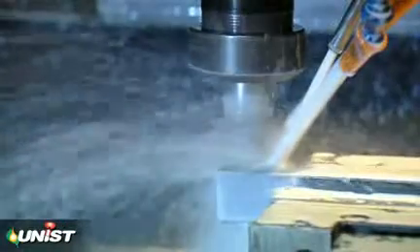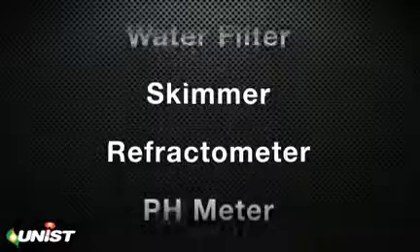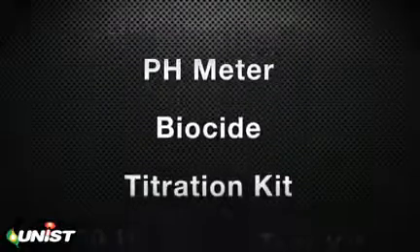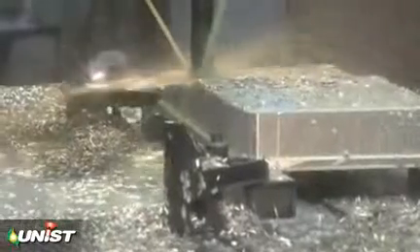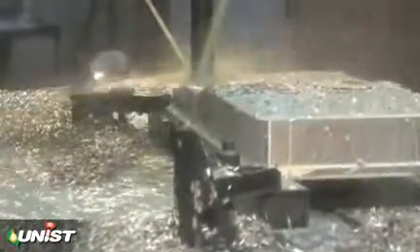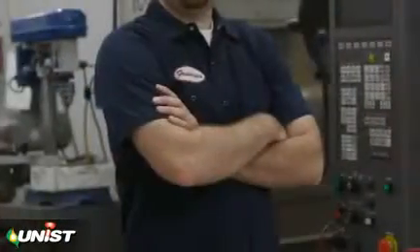One of the main problems with this flood coolant method is that you need a lot of coolant and specialized equipment to circulate, filter, test, and prevent bacterial growth in that coolant. There's no neat way to apply coolant, so it splashes all over equipment and floors, often shortening the life of machinery and irritating machinists' skin.